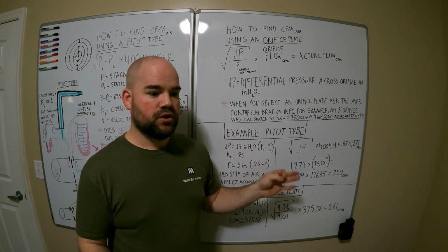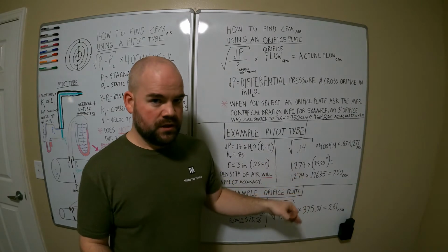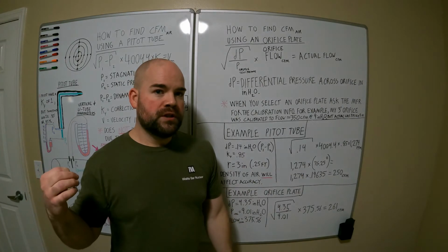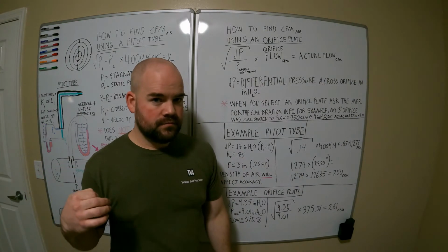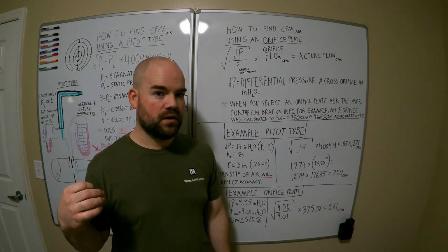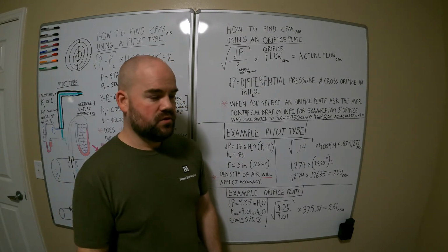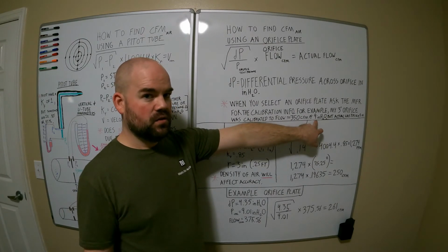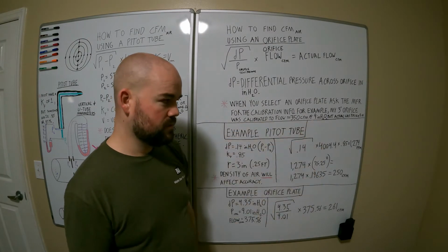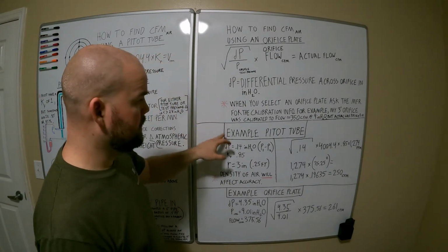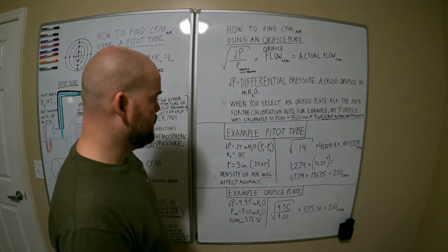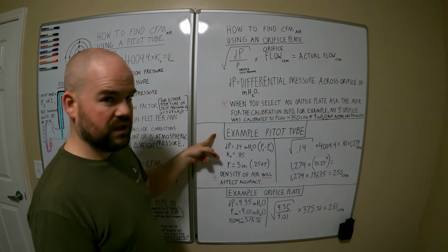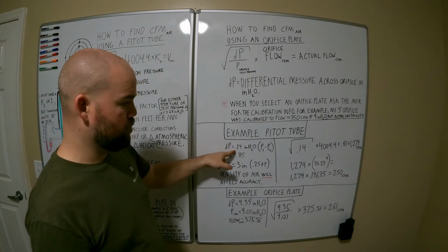You have to make sure you're calibrating your tool to the bench. Just because it flows 350 at 9 inches of water, if your tool is reading less than that, 8.25 inches of water, you're not going to have the correct flow. So you need to make sure if you're going to use an electronic device, it's calibrated to the bench, to the orifice. I'll show you how that works, or explain it to you in front of the bench.